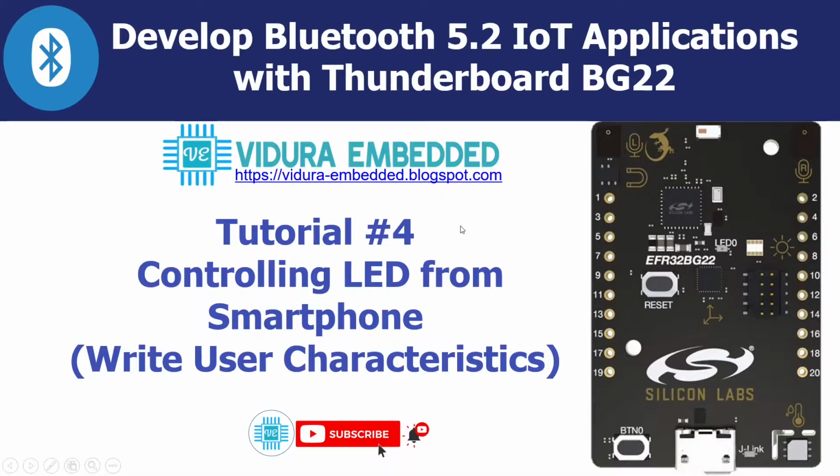So in this tutorial, I'm going to show you how we can control the onboard LED, that is LED 0, using a smartphone. So basically we use a write user characteristic. Here our smartphone acts as a client, so we will install the EFR32 Connect app from Silicon Labs, and the Thunderboard BG22 will act as a server. We will send 1 or 0 from the smartphone through the EFR32 Connect app, and that will eventually control the onboard LED, that is LED 0, available on the Thunderboard BG22. So let's get started.